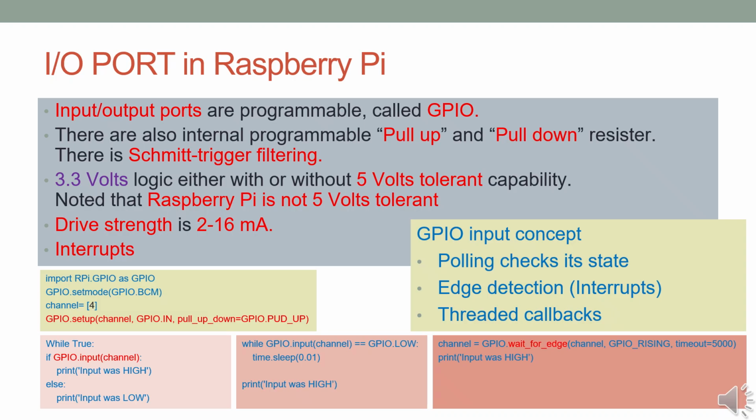Instead, it communicates through a package like RPi.GPIO, which runs on top of the operating system, usually Raspberry Pi OS. Setting up GPIO. The first step after importing the package is to configure the GPIO numbering mode. The Raspberry Pi supports two types of pin numbering. Board uses the physical pin numbers on the header, 1 to 40. BCM uses the Broadcom chip's GPIO numbering, preferred in most cases.